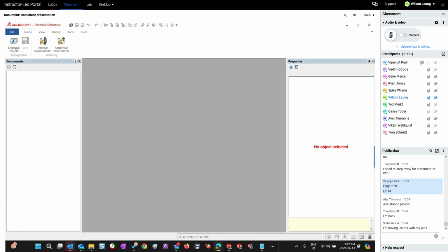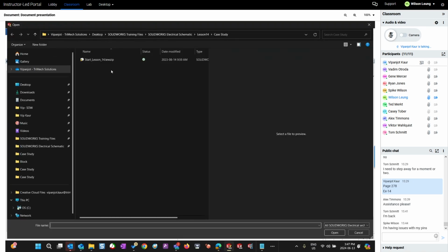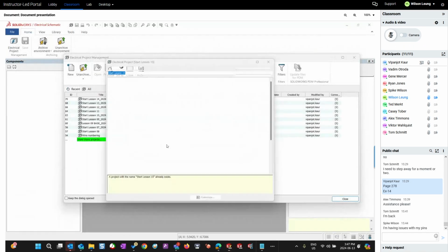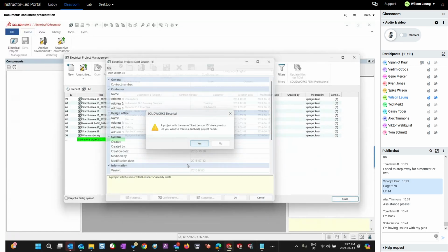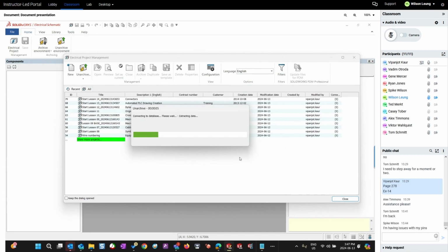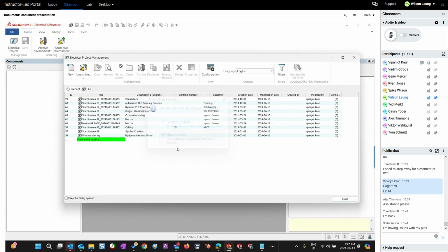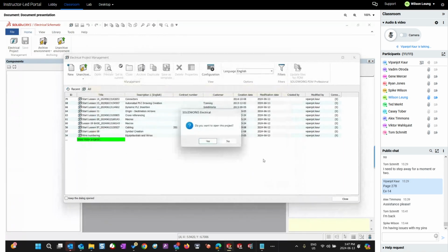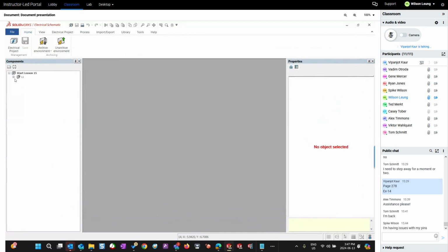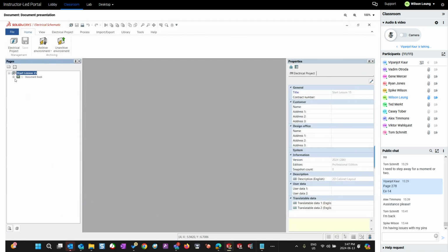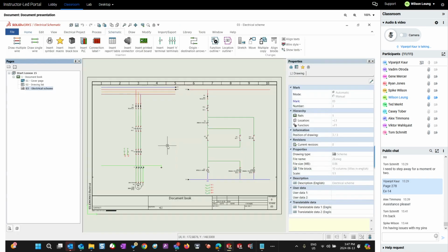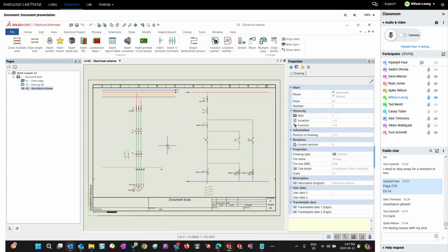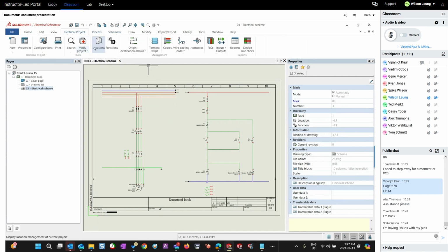So I'm going to go ahead and open this project number 15 on archive, project, open it up. So before I do anything, before I create cabinet layout drawings, I have to first create locations. So you would see when your mechanical engineer is ready. So once I create a 2D project, let's say Tom's my mechanical engineer, my 3D designer, I'll say, hey, Tom, I've already created a location for you on my project tab.